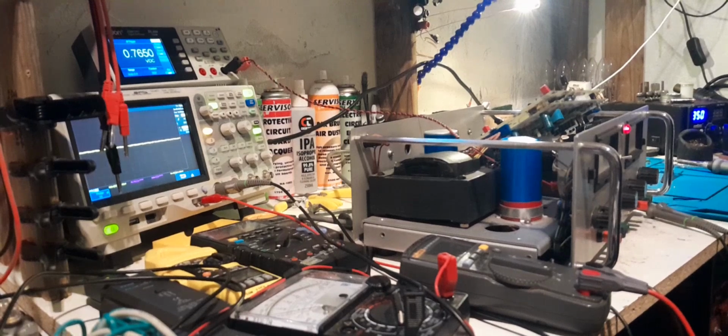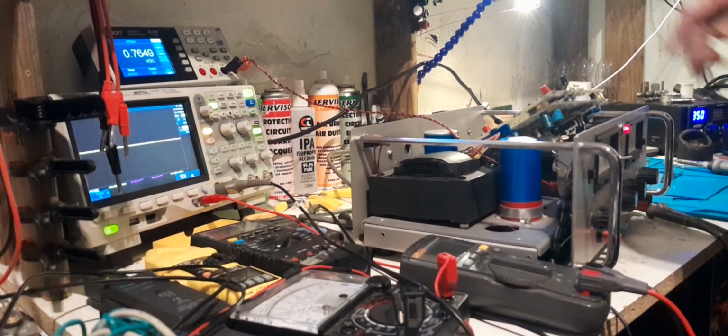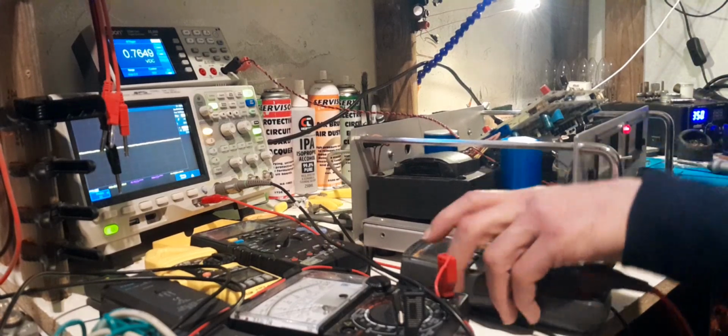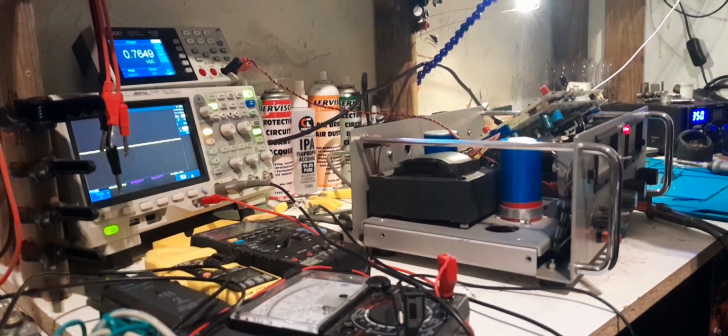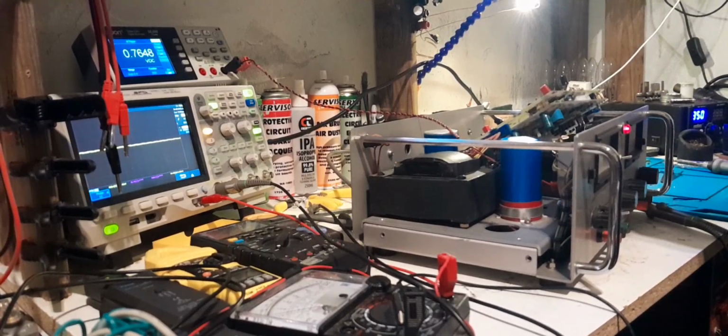So that's interesting. Maybe they're dividing down the voltage off the current sense resistor a little bit. A lot of designs do that. Sometimes it's divided against one of the rails and then tapped off of that. It's to sort of get around leakage currents that are flowing through other places, like from the constant voltage circuitry and stuff like that. More accurate, but usually you do that with a separate op amp. Like in my power supply design, the one that's really low noise and it's constant voltage at the moment, and I haven't finished the constant current because I'm trying to finish a few other little things like a little power supply in it that controls fans and panel meters.